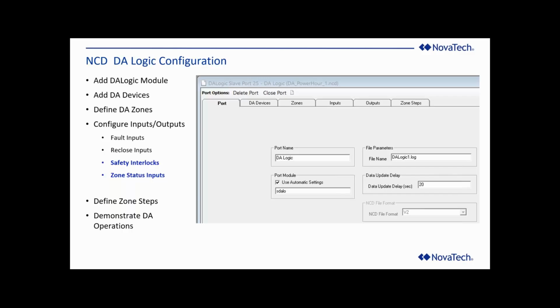That you're going to want to set according to the equipment that you're using, and it's key what kind of communications you're using. So if you are using fiber optic communications to a device on your DA system, and you're talking to everybody by fiber, you're getting very good, very fast responses.